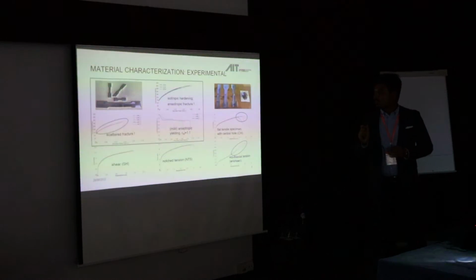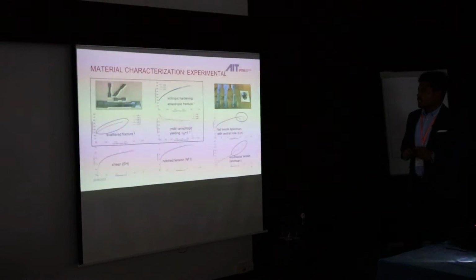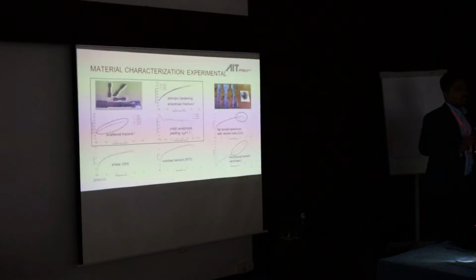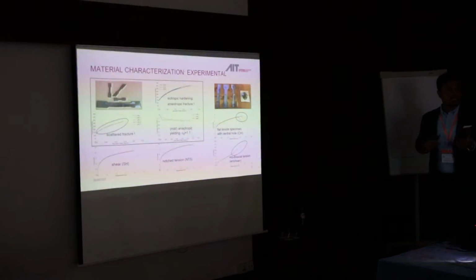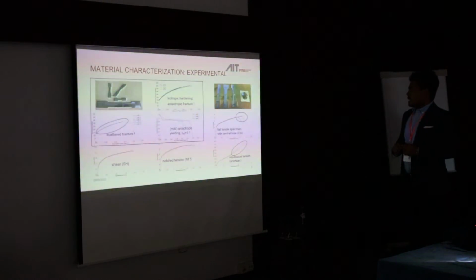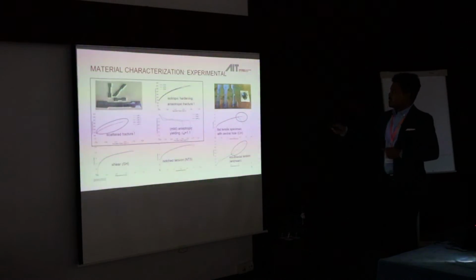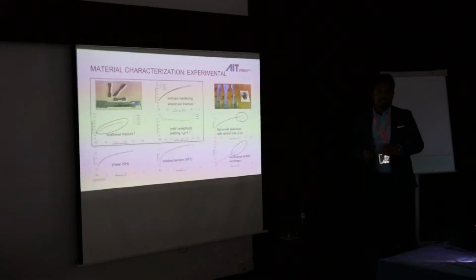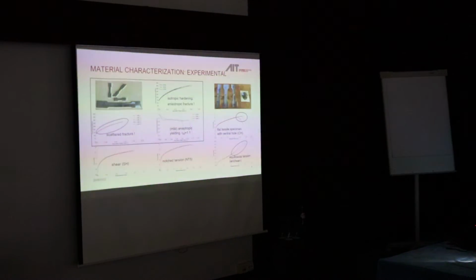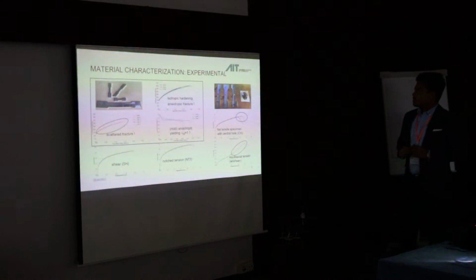What we have noticed, which is a little bit scary, is the scattered fracture and also a little bit anisotropic fracture. That's not really a good thing from a numerical characterization point of view. Additionally, I have four more test specimens you can see here from left to right. It covers stress states starting from shear up to equibiaxial stress state. It's a standard testing program.